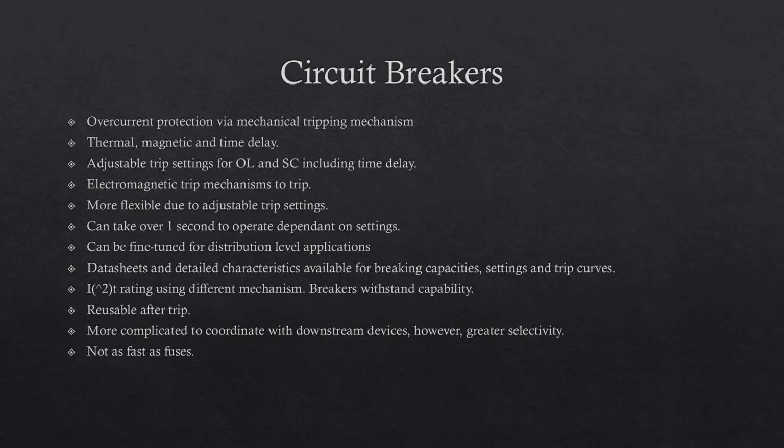providing that it's not catastrophic. Again, that is up to the intelligent operator to look at. However, they aren't one-time use, especially with such expensive equipment, which can cost maybe £30,000, for example. One great thing: you can remove the fault and put it back on. For example, if it did nuisance trip, the fuse wouldn't be able to. You can't reclose the fuse. It's popped, so to say. But with the circuit breaker, the connections can be reclosed, providing it's safe to do so.